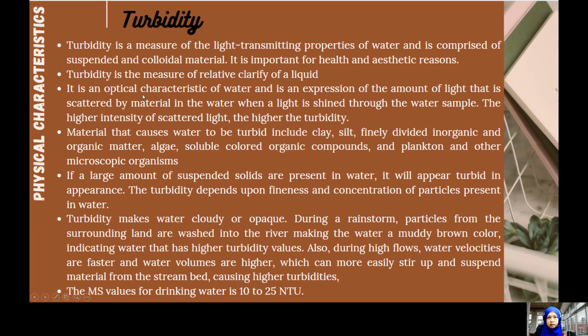It is an optical characteristic of water, and it is an expression of the amount of light that is scattered by material in the water when a light is shined through the water sample. The higher the intensity of scattered light, the higher the turbidity.